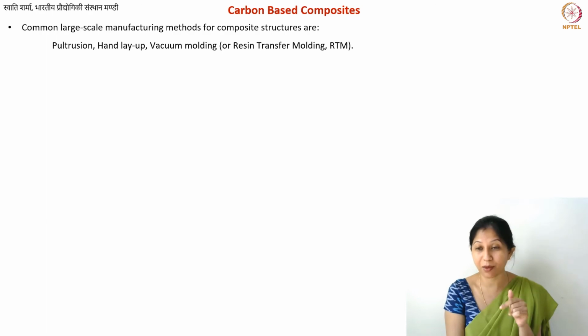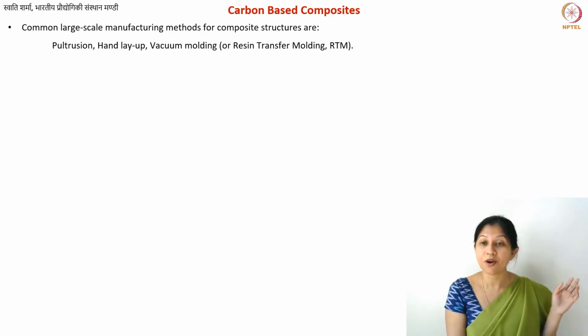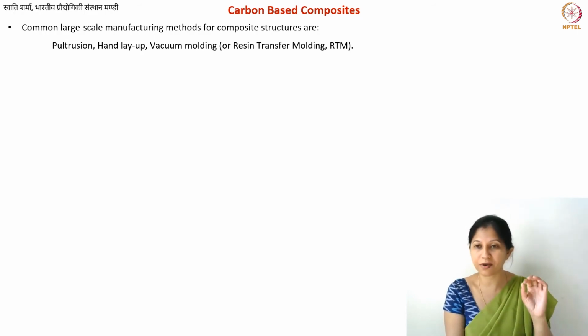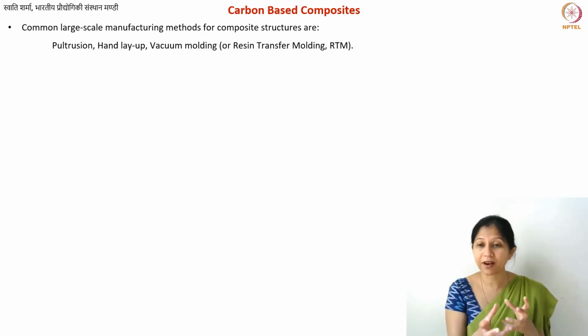However, if you want to make carbon composites, then you further carbonize these structures. So you have carbon resin structures, and you know that a lot of resins, especially phenol formaldehyde type resins, can be converted into carbon. So then you further carbonize the entire structure. However, the shaping needs to be done at this stage when you have a flexible structure, when you have the resin mixed into it. Okay, so how do you make these composite structures, especially the laminates?